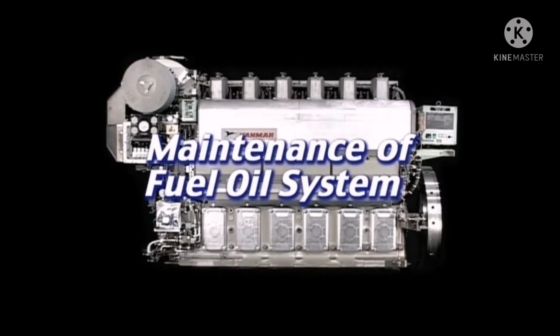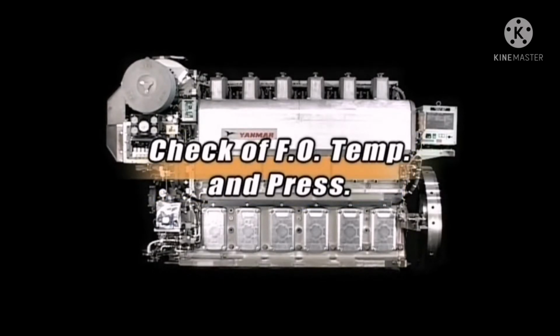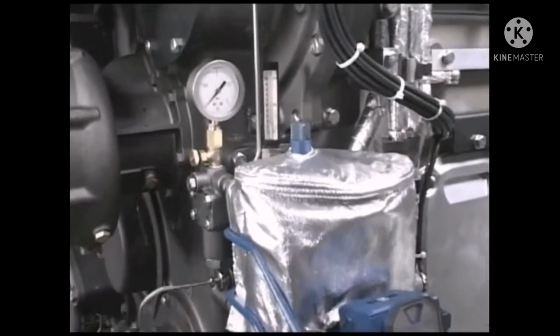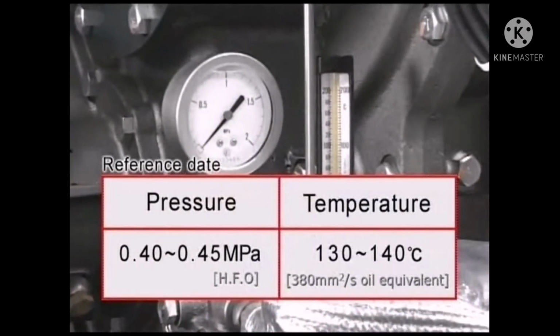In this chapter, I will first explain part of a daily maintenance check and adjustment procedures for the fuel oil system. While the engine is running, check that the pressure and temperature of the fuel oil are within the specified value that you are watching in this video.